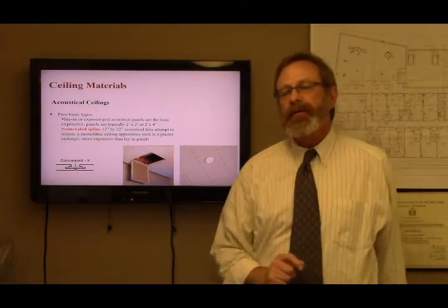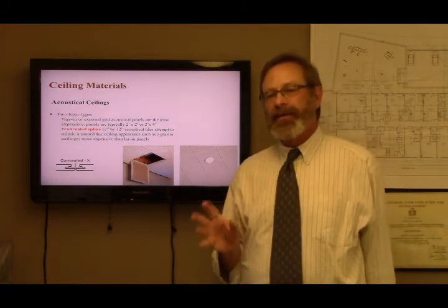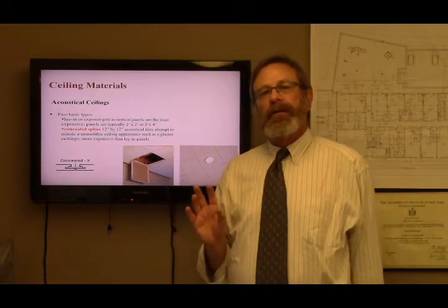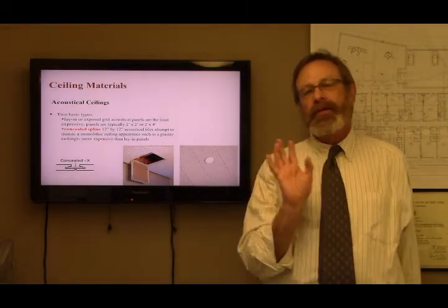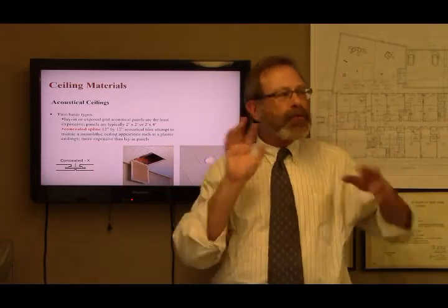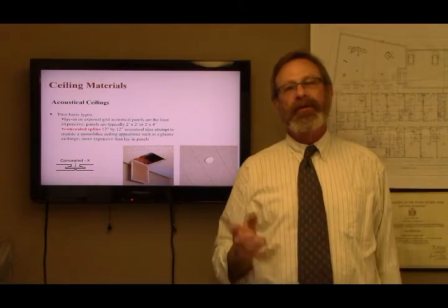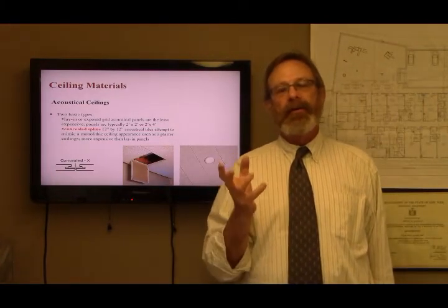Those access panels, I should say, don't need to go too often in a ceiling, whether it's plaster or veneer plaster. They only need to go where the equipment is. So there's an HVAC unit in one location that's servicing the whole area of the building. You only have to put it there, under the equipment, for access to the equipment.